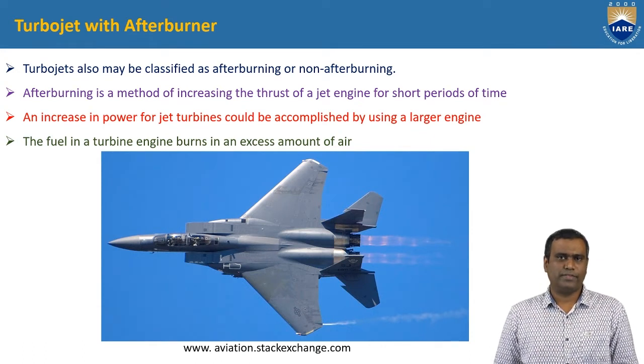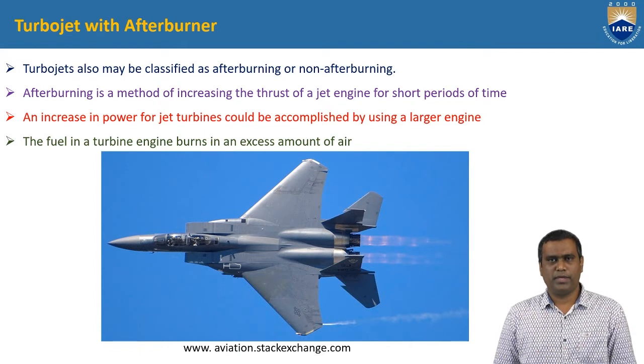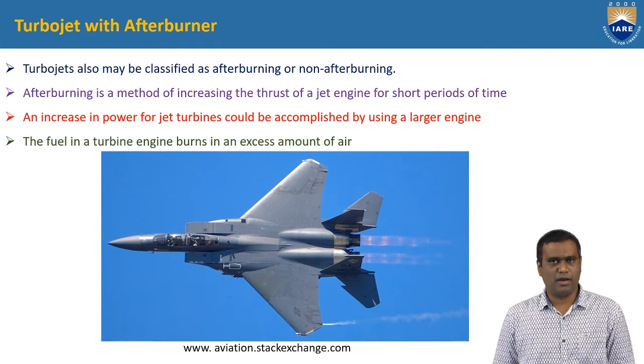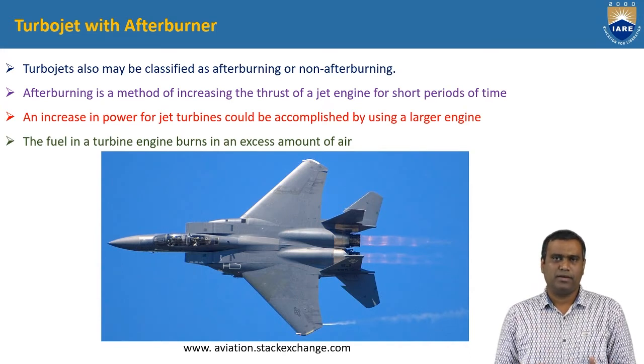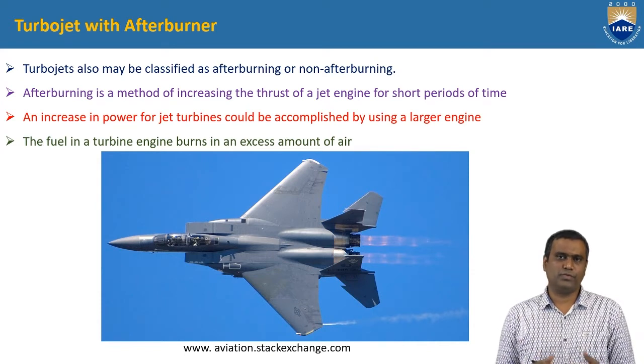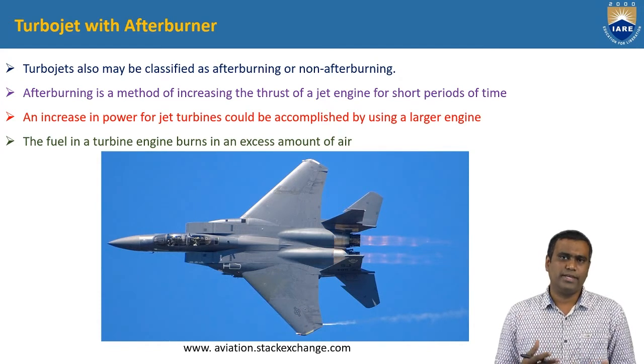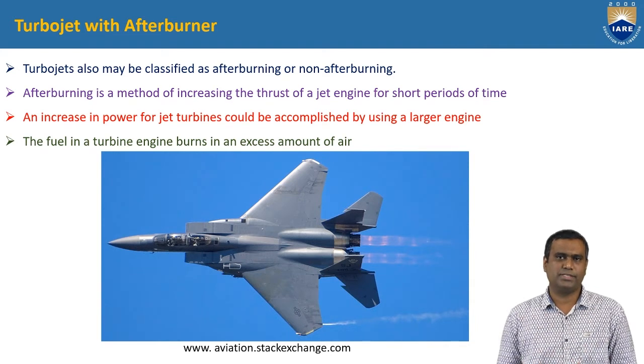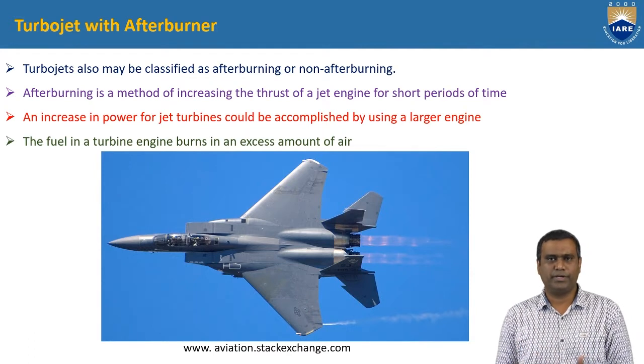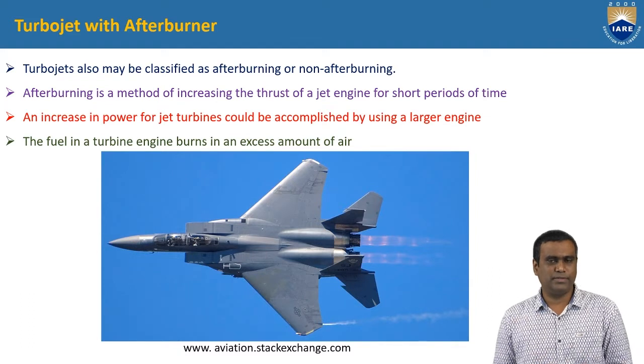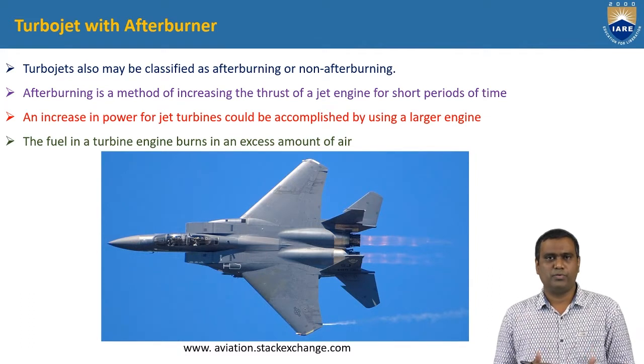Actually, the power of a jet engine could be improved by using large engines, but when we increase the size of the engine, frontal area increases, of course, which means drag increases and total weight increases. By considering these two factors alone, fuel consumption also would be increased, so it becomes more expensive. So afterburning is the best method to provide increased thrust for a short period of time.